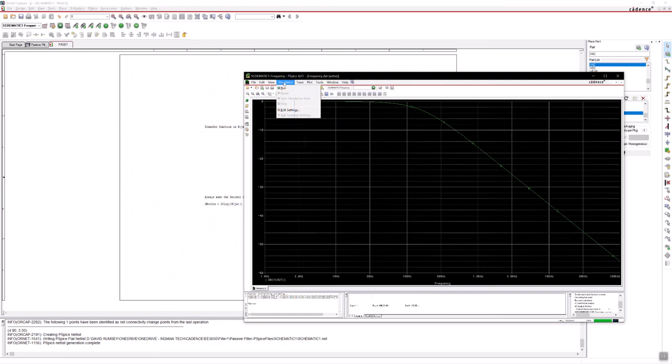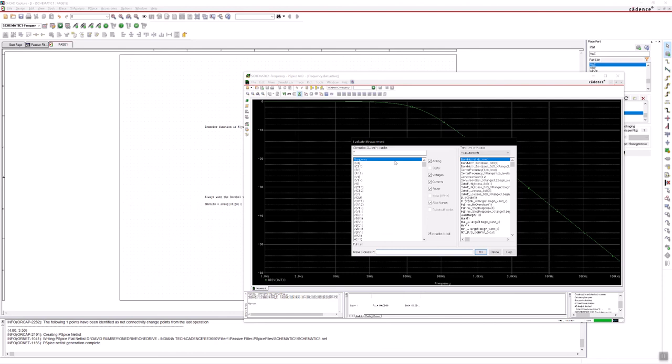Well, we're going to evaluate a measurement. And now we have to be a little bit careful here. So if we look here, we have to first tell what kind of filter it is. Well, it's a low pass filter. We can see low frequencies are getting through, but it says 3 dB.